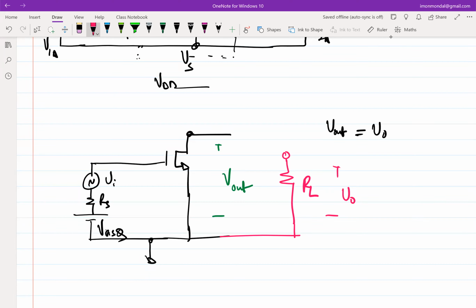Again, going back to whatever we have been discussing in the last couple of classes, for this device to work as an amplifier, you have to bias it properly, right? So how should I ensure that? Biasing has two aspects to it in a two-terminal device: input bias and output bias. Is the input bias fine? Do we have to change anything on the input side? Input bias, you don't have to change anything, right? Because I haven't affected the input terminal at all.